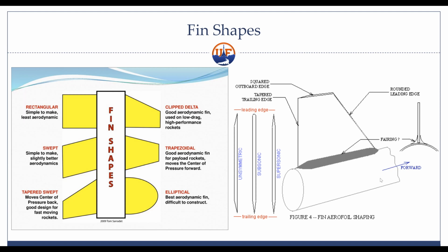Does it lower the center of pressure? The sweep? Yes, it does. It actually pulls down the center of pressure because you have more fin backwards. I think that's what you're referring to in terms of sweep.